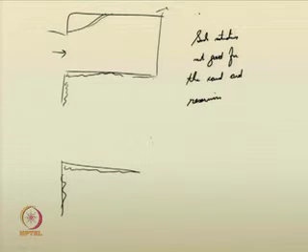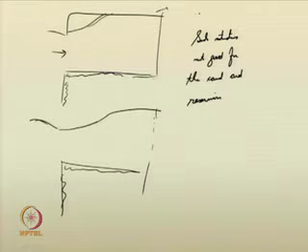You may see the surges in canals of the following form. Here it will go like this and then like this, so it will build up more. The maximum height will be at the location where it is being blocked, then it will decrease after a certain distance. Such situations are required for proper designing of canals. So, surge analysis is required in canal designing, for proper design of canals for power supply.